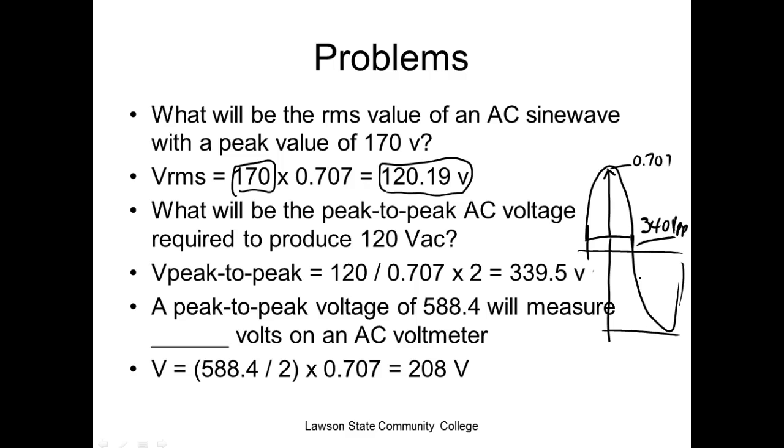The voltage, but most people just say that, but they don't understand if it steps up the voltage, the current goes down. If it steps down the voltage, the current goes up in the transformer because it doesn't change the power, right? Now, don't get this confused with Ohm's law, because Ohm's law is telling you what happens with the load. So if you raise the voltage on a load, the current's going to go up, but it's going to produce more power.